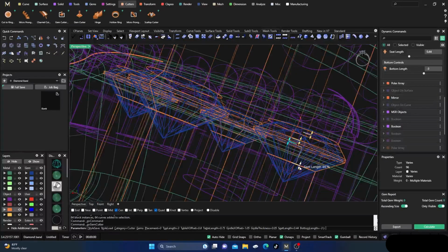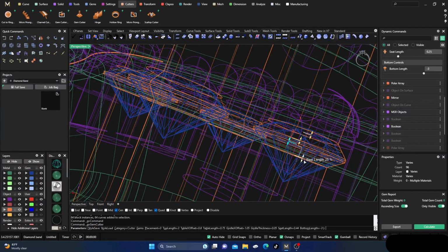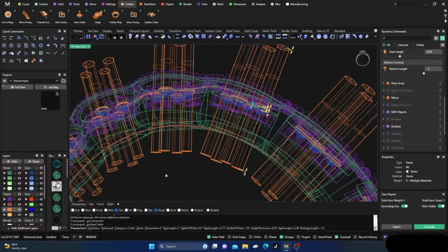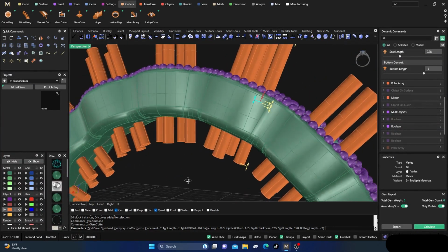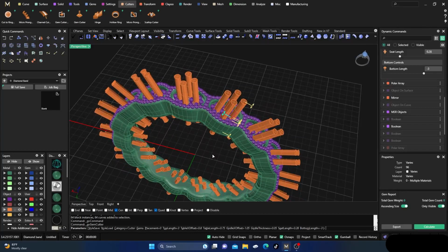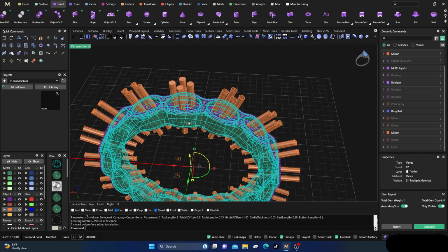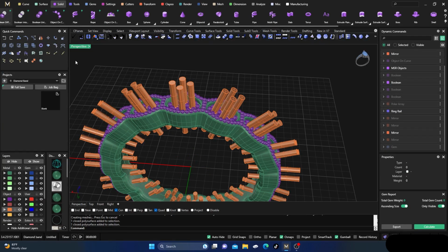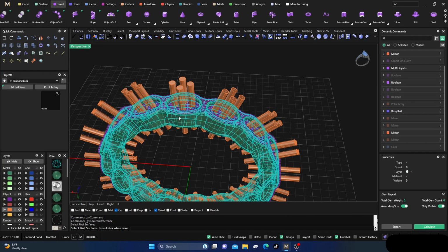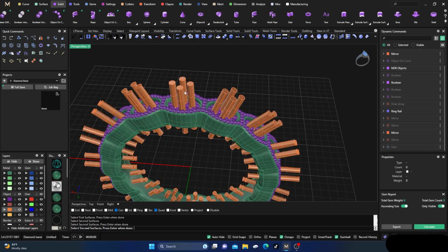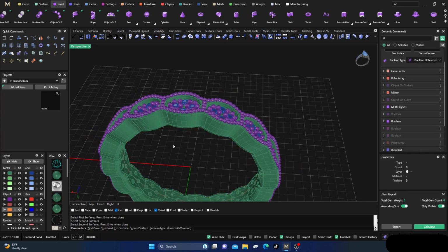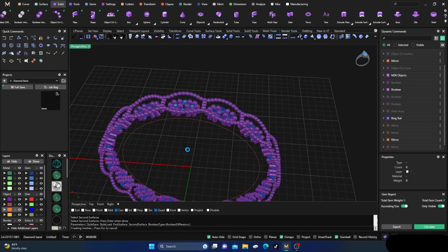Make that hole a little bit bigger. Yeah, something like that perhaps. Get some shading. Take a look. That looks okay. And we'll hit enter. And then do our, let's make sure we're still... Yep, okay. Boolean difference. Select first surface, enter. Second surface, enter. That's a lot of cutouts there, so give it a few seconds. Go ahead and hit enter.